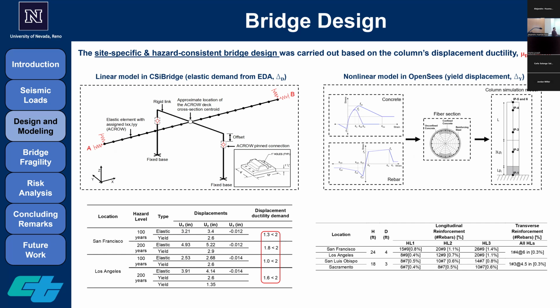Yes, that one totally makes sense. The question I want to ask you is about your hinges. The hinge that you're showing there, is it bolted both sides to the cap beam and the column? Or is it allowed to move in the transverse direction? So the transverse direction movement is restrained. It just allows rotation in the transverse direction freely and to some extent along the longitudinal. Okay, so it can move in both directions except the end point. By move, you mean rotating? No, movement is fixed, just rotation is allowed. Okay, so that is essentially a continuous beam sitting on top of the cap beam.